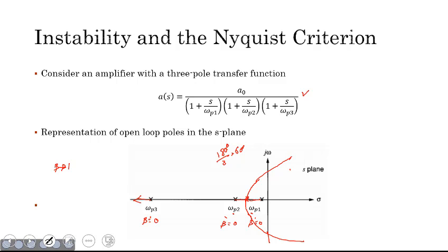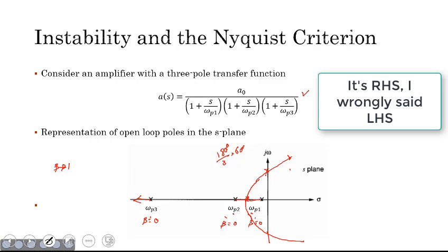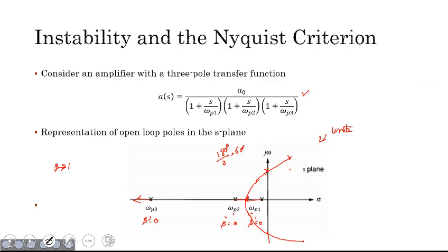So now we have poles in the right half of the S-plane. Whenever we have poles on the imaginary axis or in the right half of the S-plane, what we know is the system becomes unstable. So for a particular value of beta, we get into this particular region, and we state it as an unstable region whenever we get into the right half of the S-plane. All of that we know; it's just a kind of revision that we make here, right? So now let us see what happens.